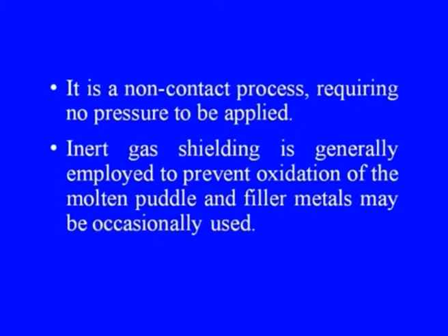As we have already seen from the schematic or the principle, this laser welding device is a non-contact device, in which there is no conventional electrode and workpiece contact, or tool and workpiece contact, and therefore there is no question of applying any pressure as well. Inert gas welding is generally employed to prevent oxidation of the molten puddle, and filler metals may occasionally be used.